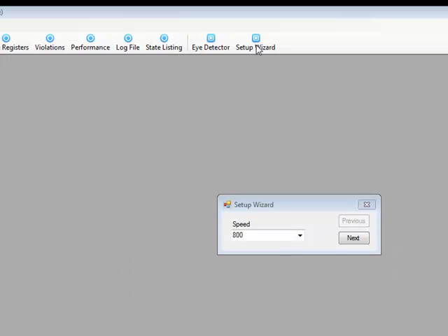The DDR3 Detective has a setup wizard to help you quickly get started with this tool. Using the pull-down menus, you can tell the DDR3 Detective the information it needs to know about your target. For our target, we have an 1867 DIMM, 2 rank, 2 gig capacity.